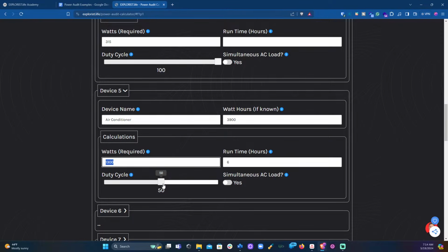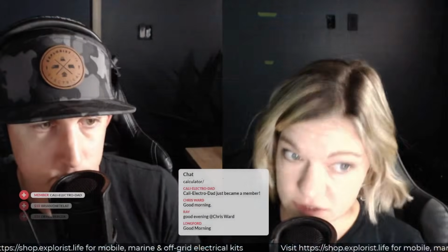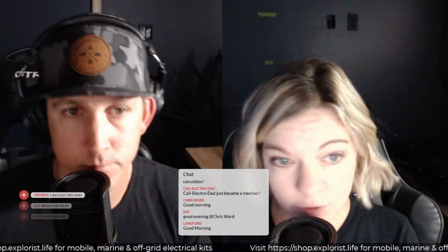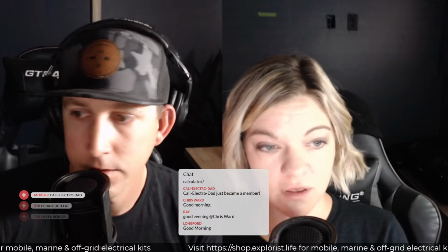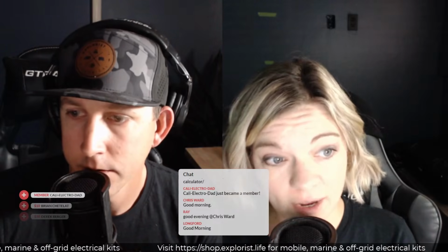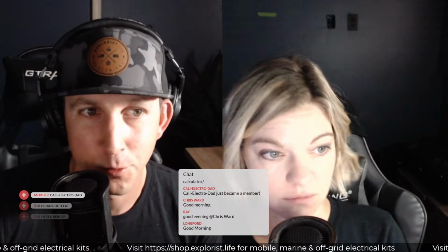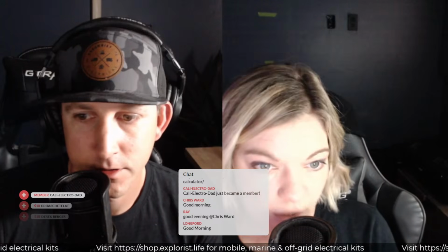And 50% is just a rough guesstimate based on that video that we put out about air conditioners and figuring out how much power they actually use. Yes. And actually, I just realized down in my notes, I have that the Nomadic air conditioner that we have is a 2-stage air conditioner. So on eco mode, we could drop it down to a total of 2,160 watt hours. And do we have the watts used on eco mode? 720. 720.